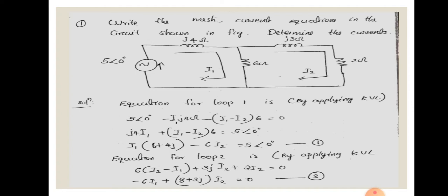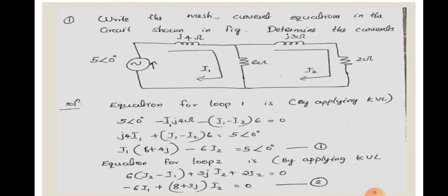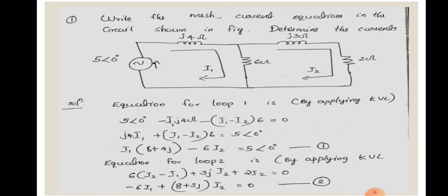Here the inductance is represented by the value j4 ohm. You know that the inductance value is j4 ohm. There will be an imaginary part in the case of AC. If you are considering AC analysis, there will be an imaginary part. If you are using capacitance, similarly we will use a minus j symbol, okay? And this circuit contains inductors and resistors. First of all, we are asked to write the mesh current equations.